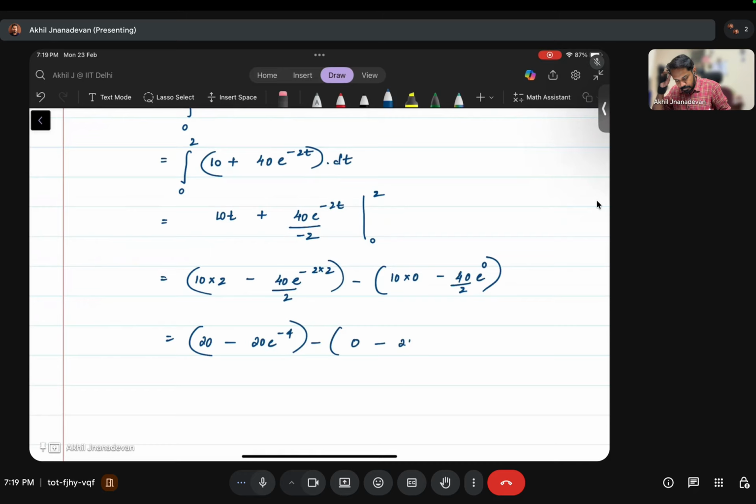Finally we get around 39.6337 mm. This is the total depth of water infiltrated after 2 hours using Horton's equation, if there is continuous ponding, which is the assumption we made.